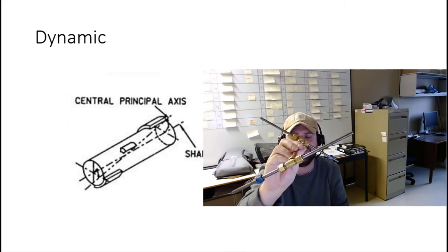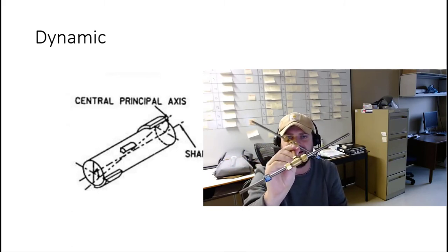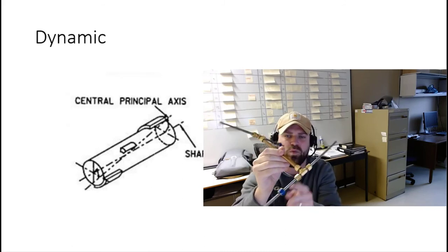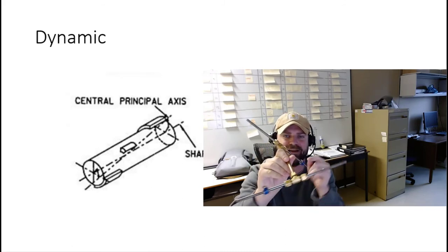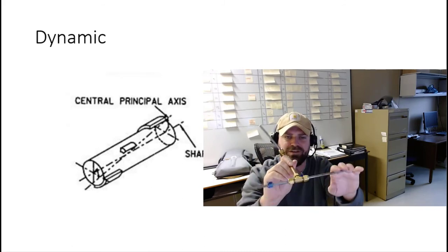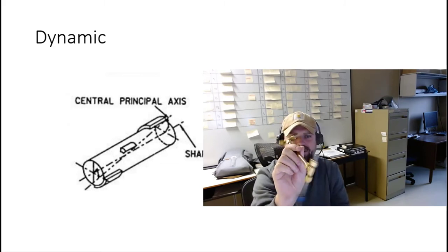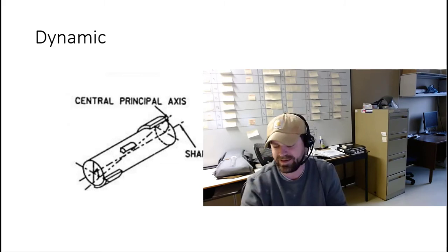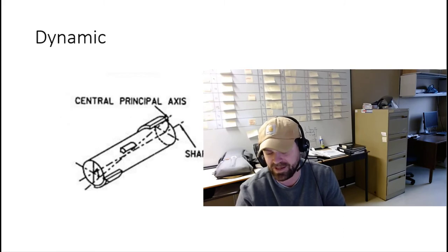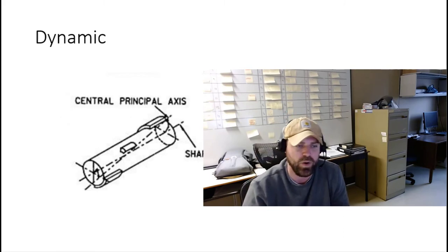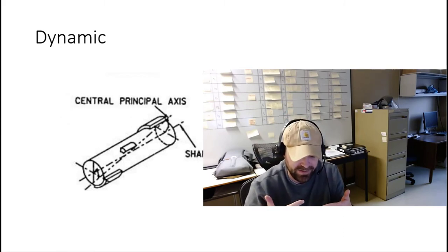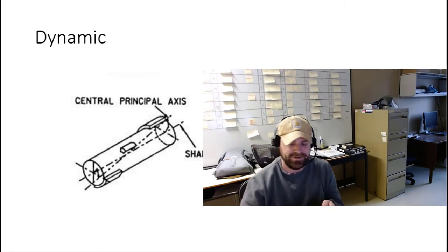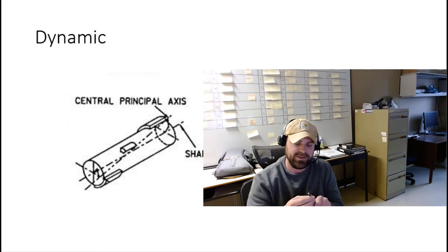It means that we have two planes. They have different amounts of imbalance on each side. They're at different angles to each other. And I could best describe this in terms of shaft alignment that you guys have done, where you have an offset alignment, but then you also have an angular misalignment. So yeah, basically those are the types of imbalance.